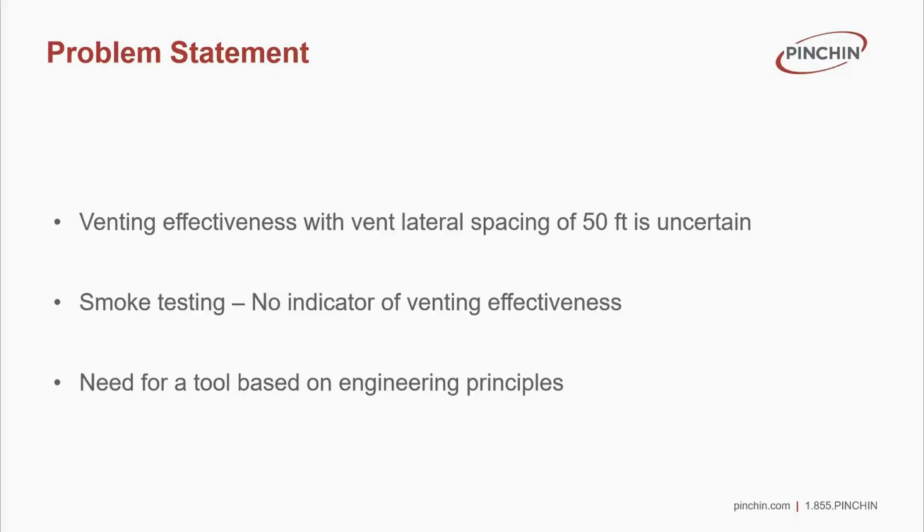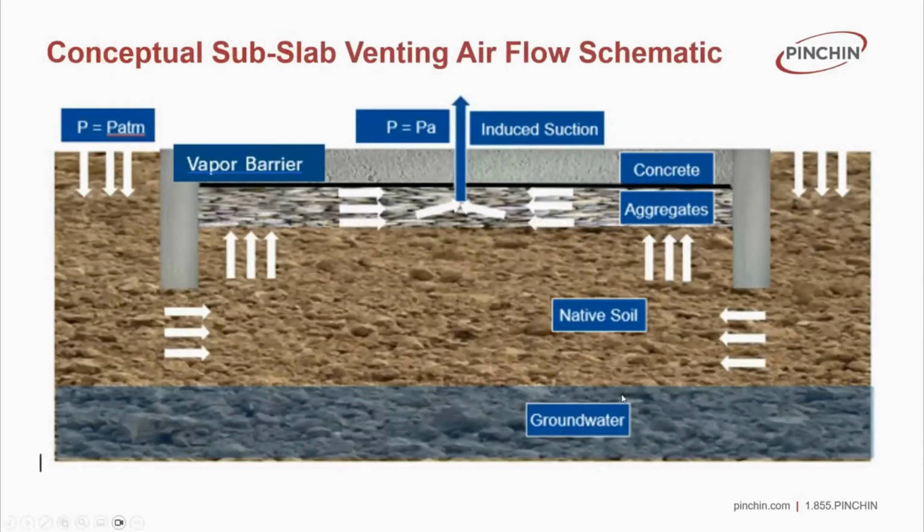All it says is that the vented out space is continuous, that is, continuity of the space between the two laterals and the laterals themselves. Therefore, there is a need to develop a tool based on engineering principles that we can rely on in designing the spacing of vent laterals.